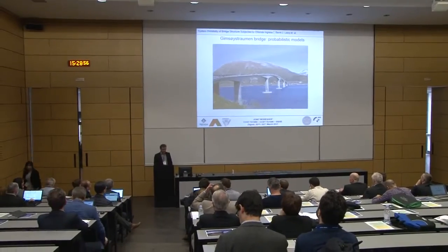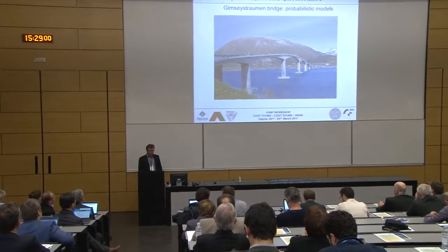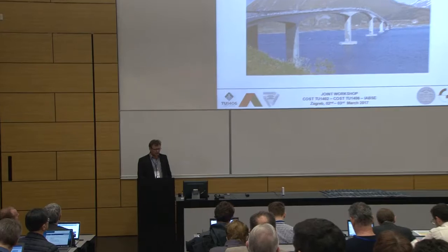problem. So the chloride will attack the concrete and then go to the armor after a while, the steel reinforcement, and then you may have, of course, corrosion and failure of the armor, and also spalling, of course, before the armor fails. And this bridge was used as a kind of test site because they had a large number of samples, chloride profiles, surface concentration.